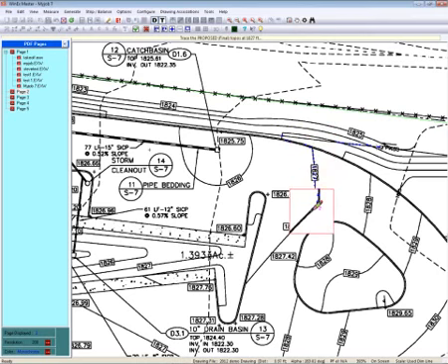You can come down. And when you get to a straight area like this, you can just click on the straight sections. And when you come to a curved area, you can just come around, hold your left mouse button down, and trace right around your curved area. You'll notice it stays, even though I went over to that plus sign, it stayed on the line. It's making some intelligent decisions about where it needs to go as I come across. So you don't need to be extremely accurate. You just need to be close to the line. And there are actually settings that you can set to either lessen the sensitivity or increase the sensitivity. So you can see how accurate that is. I mean, that makes it pretty easy to trace on screen.